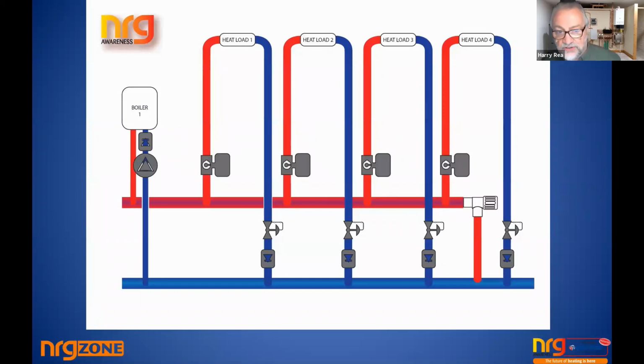In this situation, there's a very critical thing that I've never heard anyone discuss clearly, and to my mind, it's critical. Say, for instance, the boiler has a thermostat on the return. For the water to reach the return, it has two choices. One choice is that it can go through the header, up through a zone, back down, and back on the return. But if the returns can't get water because, for example, some of the zones are turned off and enough water can't get through the zones to come back around and turn off the boiler, it is delivering enough heat for all of the zones.